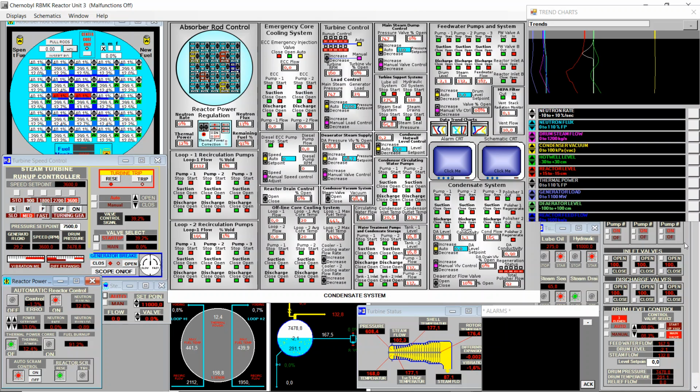So now I will start rolling back the systems to the position for less than 80 megawatts. I will switch off pumps 2 and 3, the feed water pumps, and close the discharge valves. I will let the inlet open in case I need to turn on one of the pumps quickly for some reason. I will switch from 3-element control to 1-element control in the hot well level, and switch from the main valve to the startup valve in this same system.